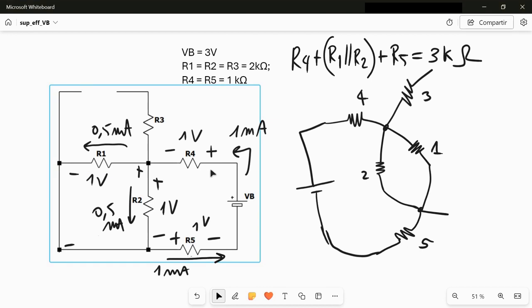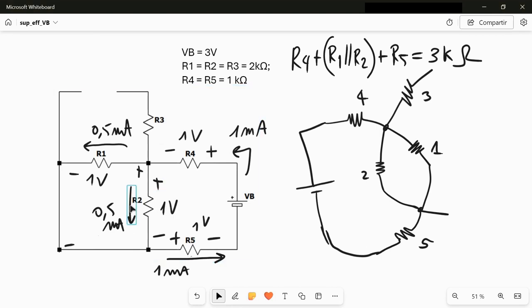And actually also therefore the current and the polarity are opposite to the sign that I chose at the beginning. This thing happens also for R5. In R3 I have nothing. And in R2 actually the polarity and the current direction are the same as the ones that I stated at the beginning of the problem. So for the voltage I will put -1, +1, 0, -1.